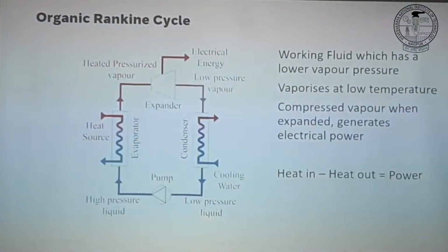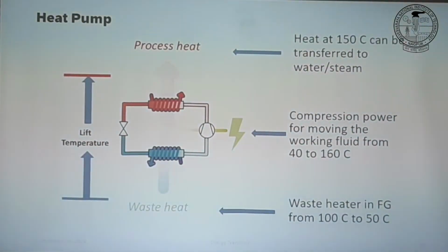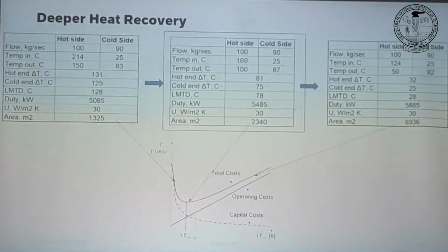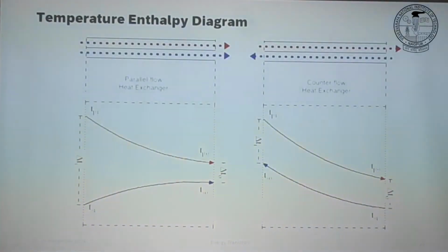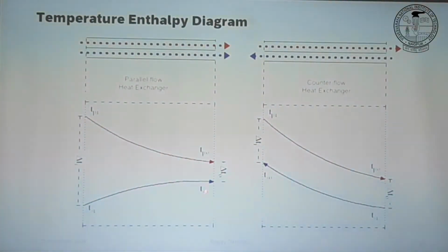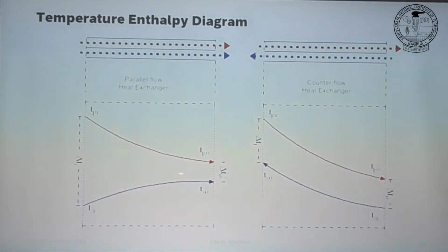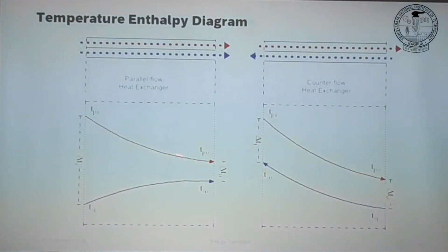So theoretically, can we in that parallel flow heat exchanger, can we cross that outlet flow? Which one? The parallel flow? Here? So normally you cannot. Theoretically yes, but what you can do is have two passes, right? So you can have two passes on the tube side, so it goes like this and here, right? And then you can have a cross. So first pass it will be co-current, right? And in the second pass it will be counter current.